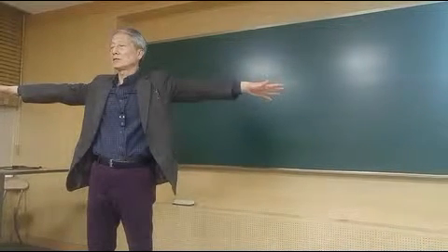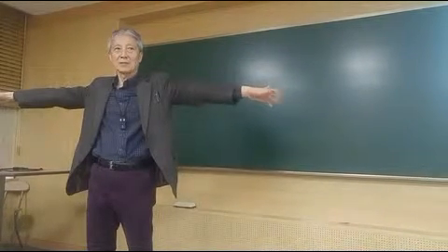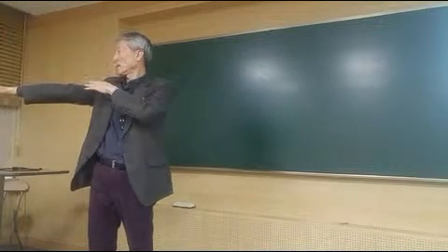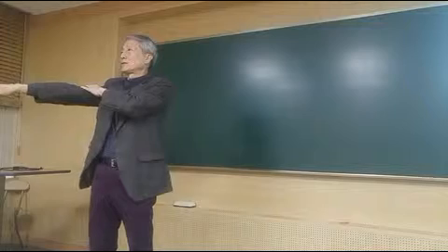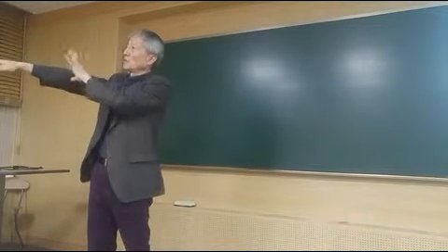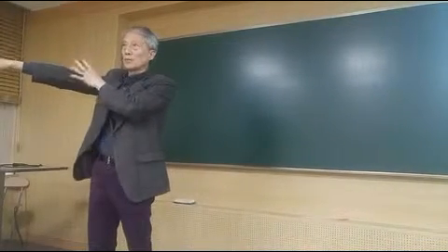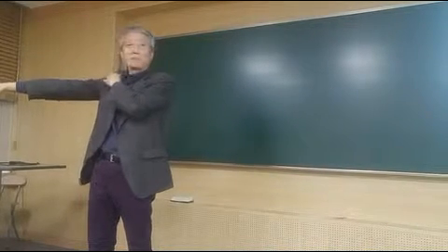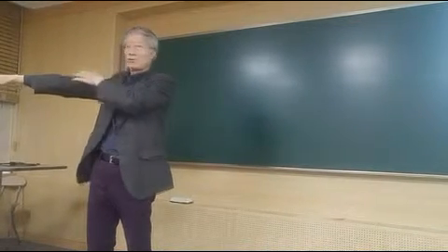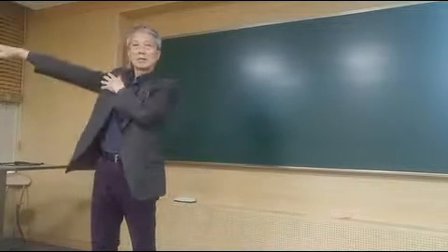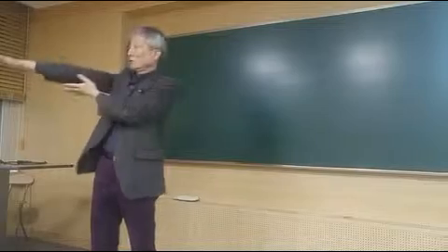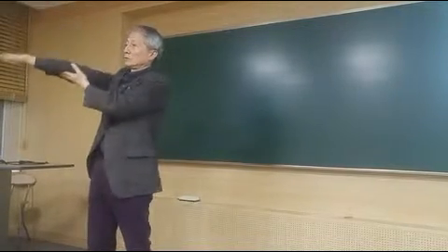So I designed the airplane, let's say, in the initial design. I found that the area is enough to make the lift force and the shape of the airfoil is okay. But I found that the connection part of the wing and main body is structurally weak, because half of the lift force should come in here.